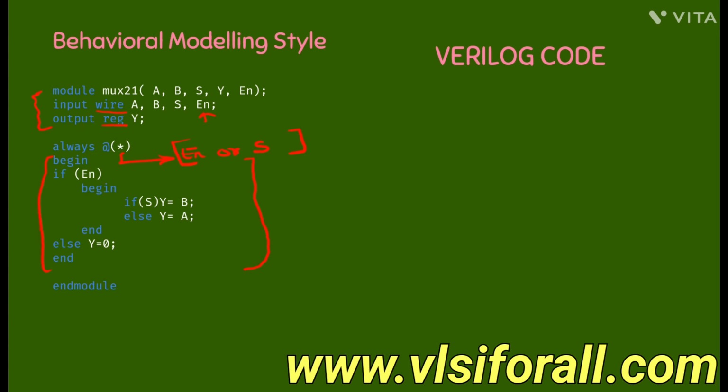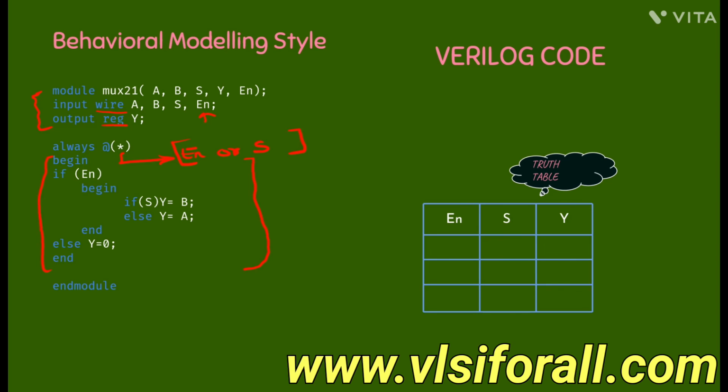For functionality, we will refer to the truth table of the 2:1 multiplexer. Here is the truth table that we can use in order to write the modeling style. From the first if statement, if enable is 1, that means if enable is true, then we begin, and we have another nested if else statement. If s is 1, that means enable is 1 and s is 1, then the output should be b, else if s is 0, then the output should be a.